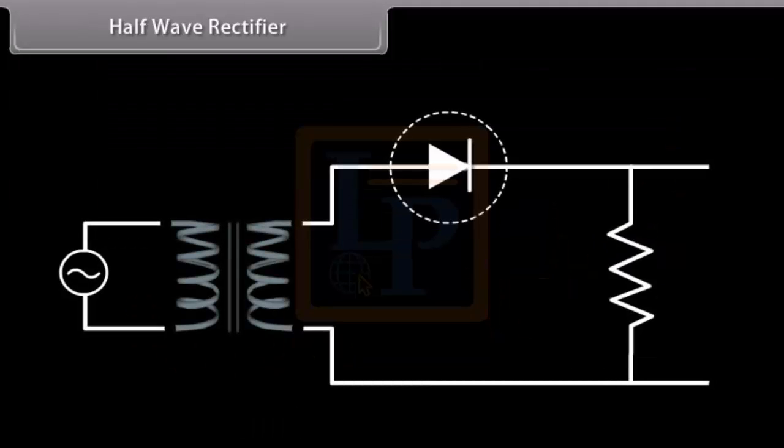Half-wave rectifier. The AC signal to be rectified is connected across the primary terminals P1 and P2 of a step-down transformer. One of the secondary terminals S1 is connected to P region of junction diode, while the other secondary terminal S2 is connected to N region with a load resistance RL in series. The output voltage is taken across the load resistance RL.